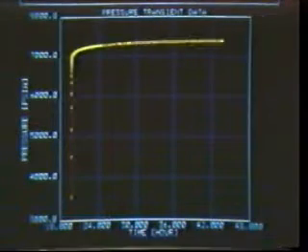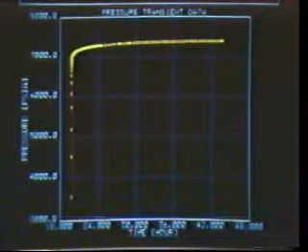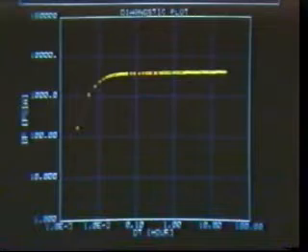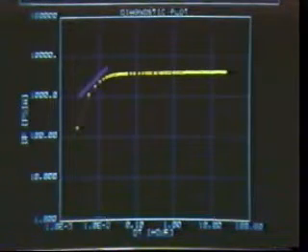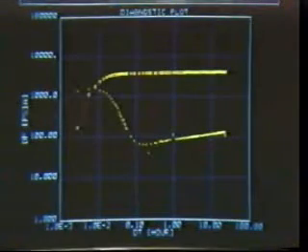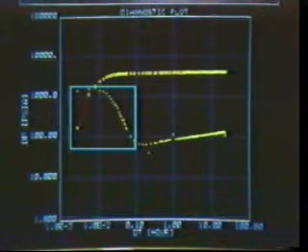We first construct a simple Cartesian plot to check for the presence of any anomalous tool response. The tool seems to have worked properly. We next construct the log-log data plot. We note the presence of wellbore storage as indicated by the unit slope of the early time data. Next, we display the values of the derivative. The derivative curve displays the hump characteristic of wellbore storage.